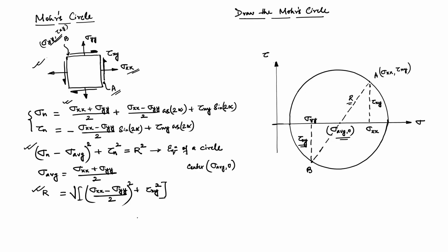From this Mohr circle, if we identify this point and this point, these are the two planes along which we have only sigma and there is no tau. So, these are the points on the Mohr circle that represent the principal planes. So, this is sigma n, recall this is the maximum value, and here we have sigma n minimum value.